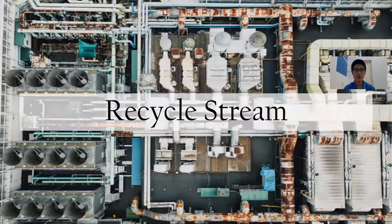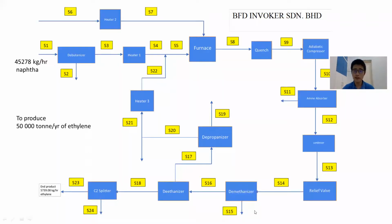So now we will proceed to the next slide, which is the recycle stream. Basically, our recycle stream will start at the debutanizer, and then after that, it will enter the depropanizer. After that, it will enter the purging system. The purging system will separate 50% of the desired product to enter heater 3. After that, the desired product will connect with the outlet stream of heater 1 to become one stream to enter the furnace for the reactions to occur.